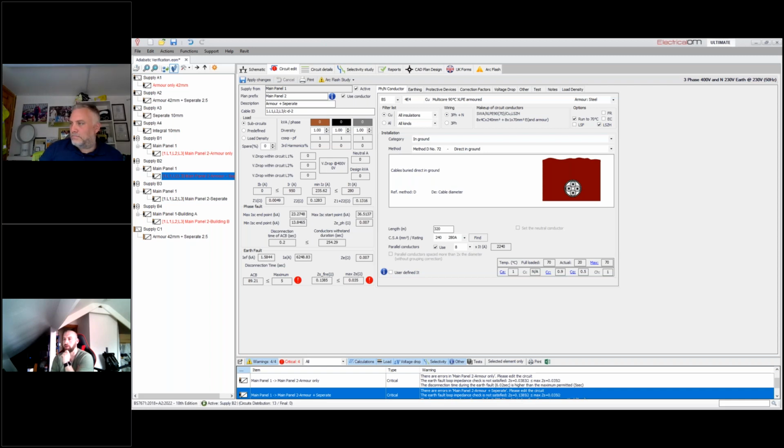There is a separate paper from what we were looking at today, in relation to conductors buried in the ground, but that's more specifically around the ground conditions, ground temperatures, and how that affects the effective current carrying capacity of the cables. It's not looking at anything to do with changing the physical, impeditive or reactive properties of the conductors. So in this particular case, no.